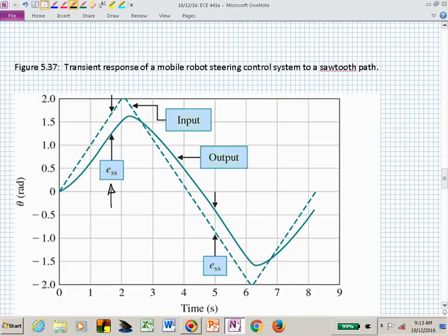If 5 is far enough in or after an infinite amount of time, not theoretically, practically, which is 5 tau. Is that clear? So even though you're bouncing back and forth in this sawtooth, you now have to wait until you're settled, you've passed your settling time, and then you can start worrying about your steady state error.